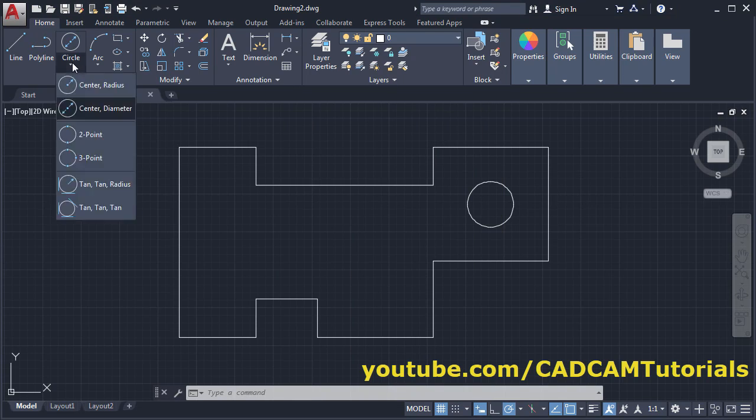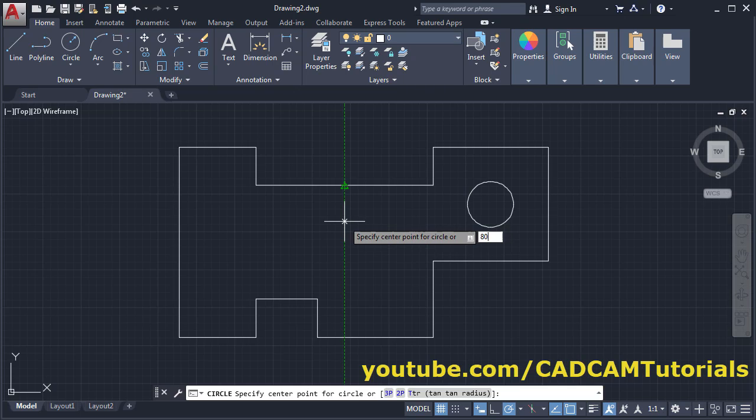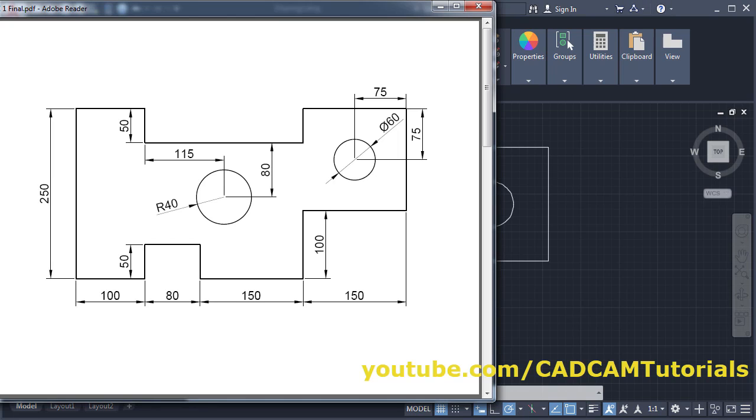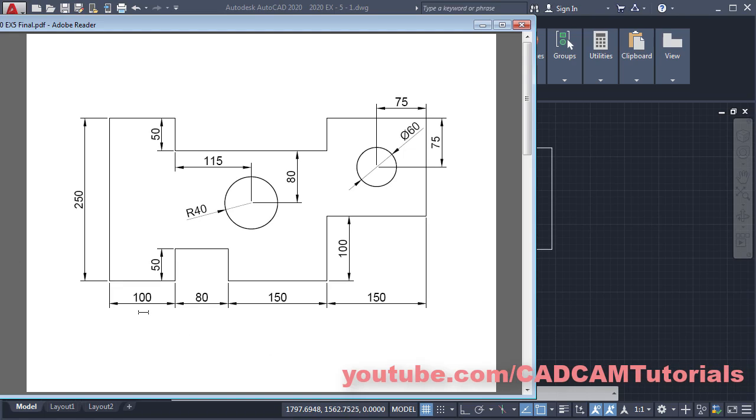Then click here and select center radius. Then track this point and give the length of 80. Enter and give radius of 40. Enter. So this shape is ready. We will start dimensioning this drawing. At first we will give these dimensions.